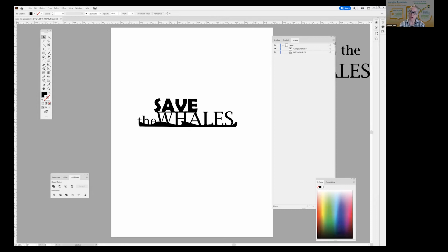So the steps that I'm showing you are how to get your vector document to be compatible, or I should say importable, to be able to import into Tinkercad. And that's the value of this particular tutorial. The important thing to remember is that you have the one and only logo design that you want to have. You shouldn't have anything else on the field.